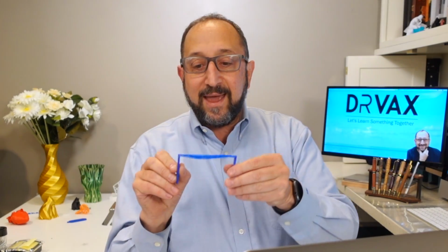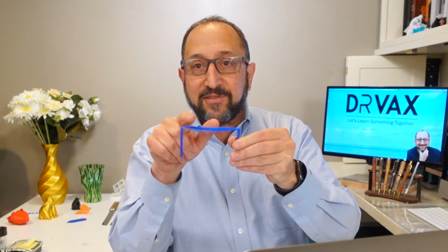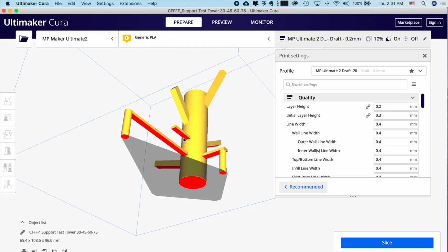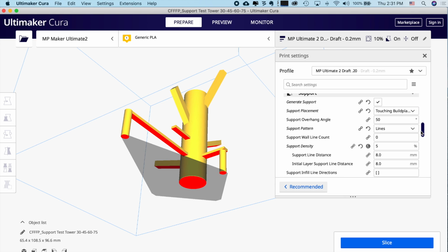Well, as the structure moves from vertical to closer to horizontal, gravity pulls on it. And when it gets far enough over, it will start to bend if we don't support it. It won't print properly. In a case like this, the bend is so severe that these top layers had nothing to even stick to. So this is showing you those layers that Cura believes are too steep.